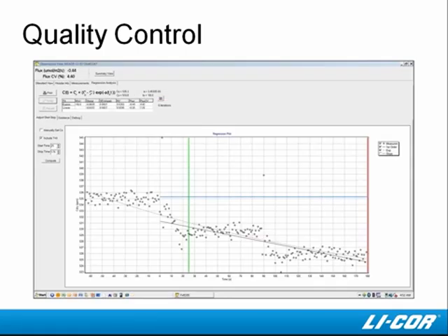During the screening for instrument diagnostics, we found several records with little or no flow. Without flow, the measured change in CO2 concentration is typically small and may be upward or downward. The regression analysis shown here was from a record with no flow. The stepwise decrease in CO2 concentration leads me to believe that there may have been a flow blockage which caused the low flow.